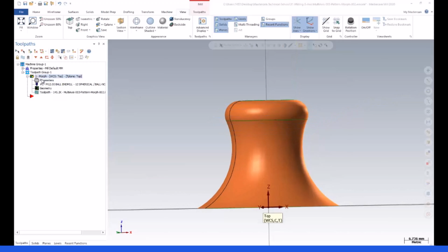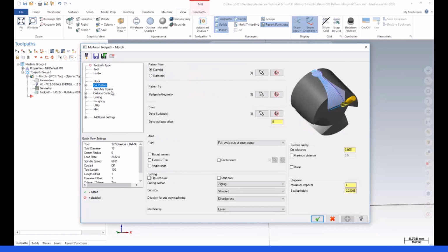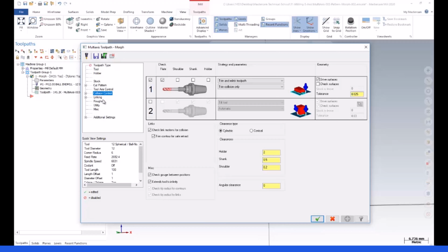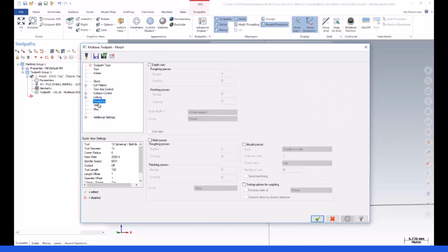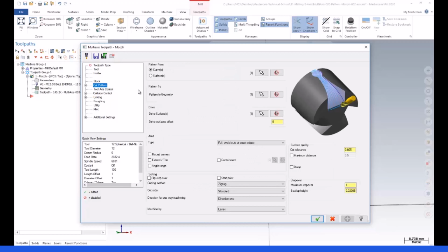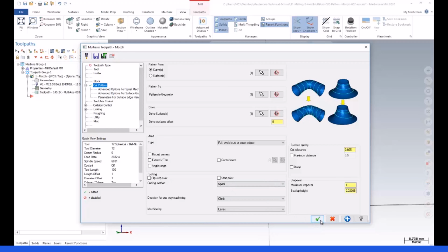Okay, what else can I do? Maybe in the cut parameters, you can see the drive surface here. And of course, when I turn back to linking parameters and roughing, it's also possible, but I don't want to make any roughing in my toolpath. In the cut pattern parameters, in that case, maybe we can use the spiral here as a cutting parameter.